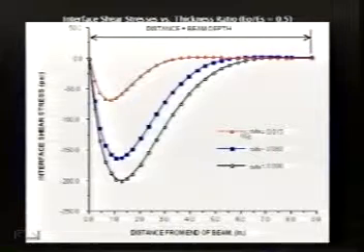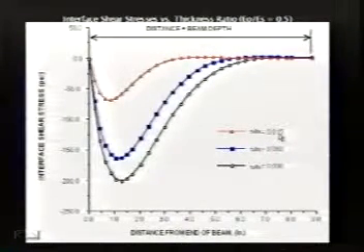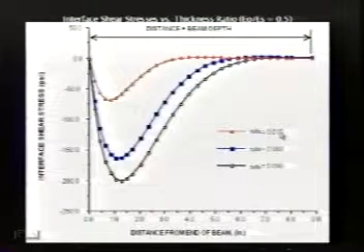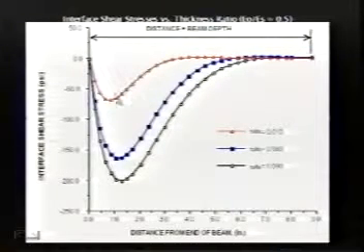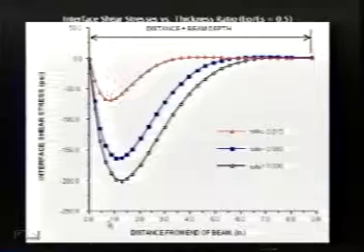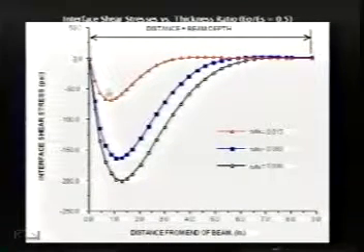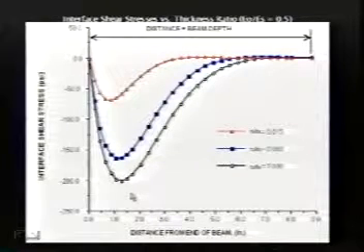This is a ratio of thickness of the overlay to the thickness of the slab. This is a pretty thin overlay. This would be a matter of a few millimeters in thickness, going all the way up to about 0.09. So for a 6-inch slab, that'd be roughly a 1/2-inch thick overlay. But again, notice that as the thickness increases, the red is for the thinner thickness, the white is the larger thickness. Notice that as the thickness increases, the stresses increase in the overlay.